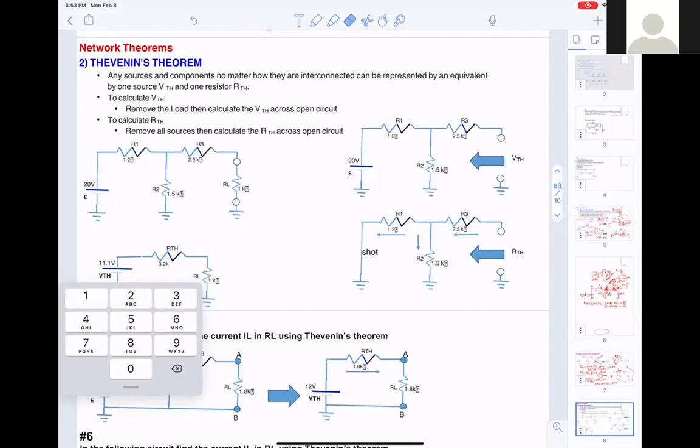So there was leakage current. The only way I could discover why the board was malfunctioning was that the leakage path had less resistance than this huge 15 megohm resistor. And I solved the problem by measuring voltages.